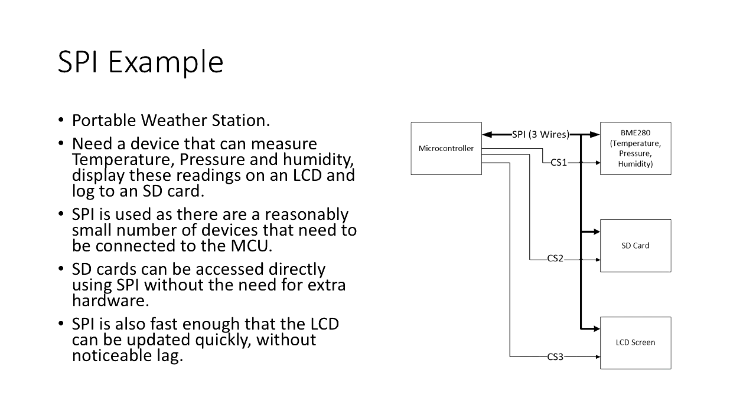People might ask about I2C. I will come to how people thought about I2C. But with SPI, please understand, from the microcontroller you got 3 lines going to each slave. Your sensor has 3 lines, SD card 3 lines, LCD 3 lines, and the microcontroller can select which one it is communicating with. So that is what I mean by 3 going here, 3 going here, 3 going here, and then you are selecting which one. So that is SPI.